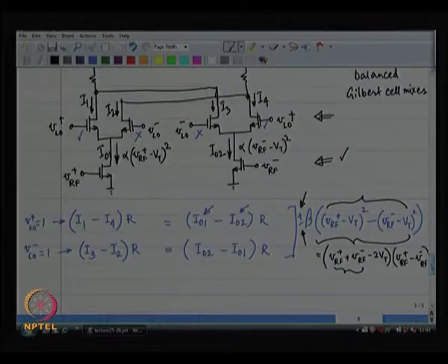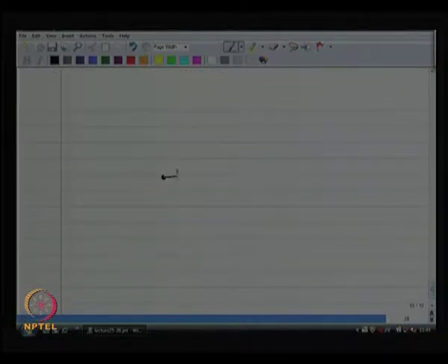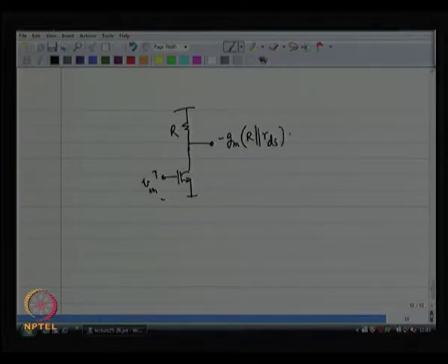and how do you linearize a circuit? So, think about this. You apply V in over here, small signal, and the output you get, if V in is a small signal, then the output is minus gm times R parallel rds times V in.